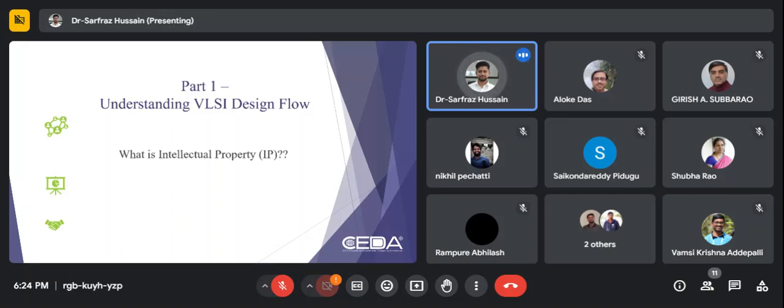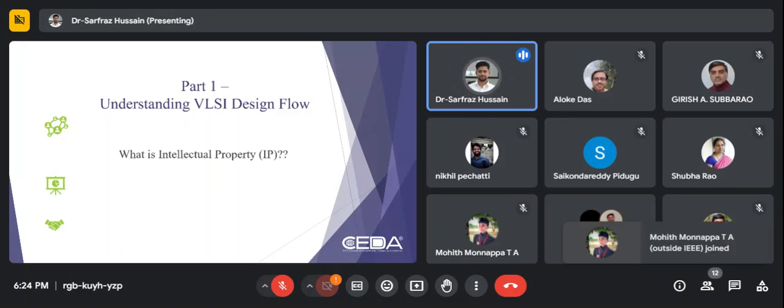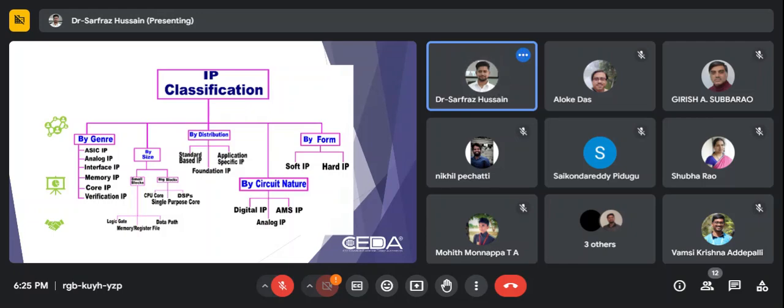So that is what we actually do in analog IPs and digital IPs. These are already predefined. It means Global Foundries or any other fabrication lab already has the definition of what will be the size of the particular gate, what will be the shape. If there are three inputs, what will be the size? If there are two inputs, what will be the size? These are all predefined.